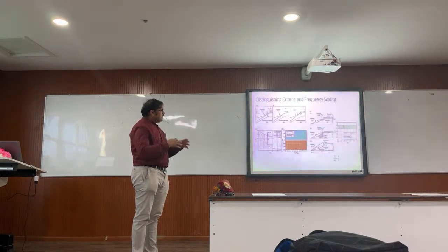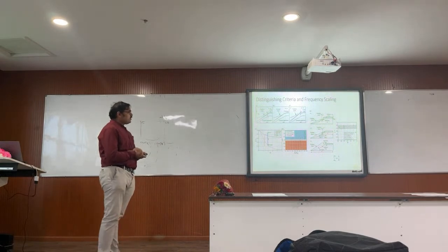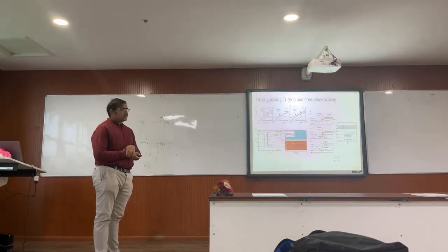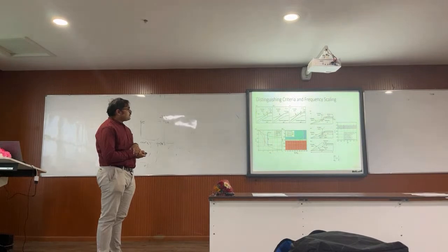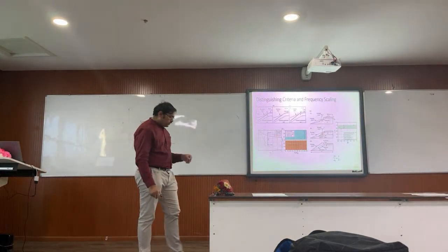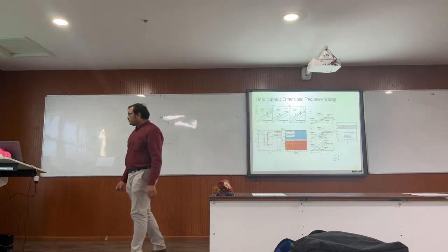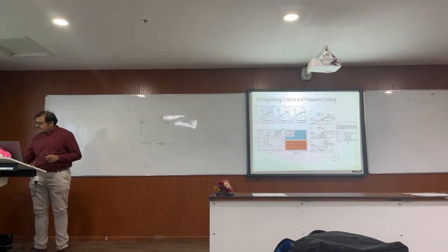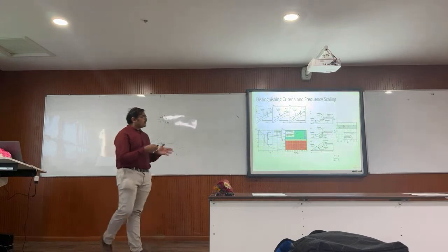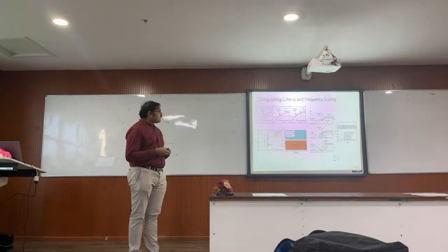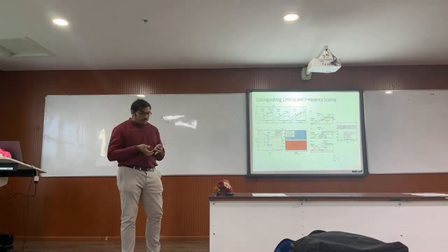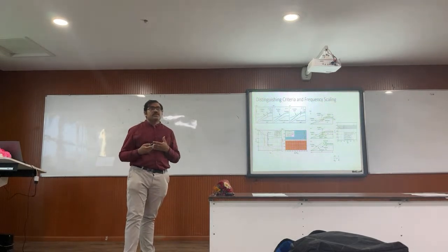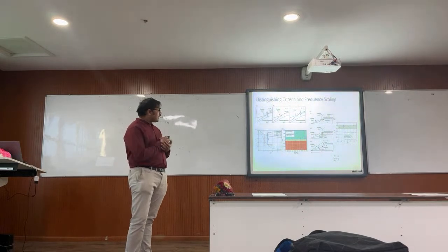So, we summed up all of these studies, and what we found was that there are two modes of oscillation. One is very large amplitude, the other is small amplitude oscillation. This kind of oscillation has been found in other intakes by several other people, and they said, we found this particular oscillation, this is the frequency, but it was never clear where we can draw a boundary, a line as to when we would get low frequency oscillations, when we would get low amplitude, when we would get high amplitude.